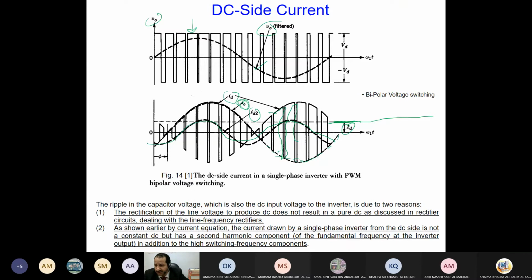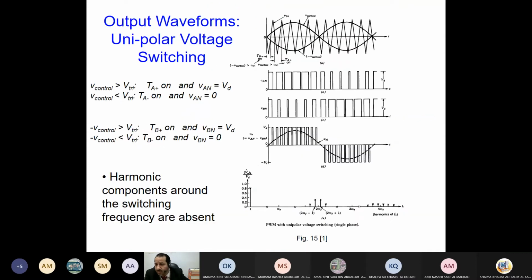If it is, let me say, a solar cell, the same thing. And the second one, this distortion happened because of the AC part produced in the circuit. And this AC part has double frequency, which will distort the current entering the inverter. The inverter needs to handle this also. If we modify or tune the filter elements, tune is the right word, we can reduce this harmonic much. And it will be good for the inverter, for the load, and for the supply.